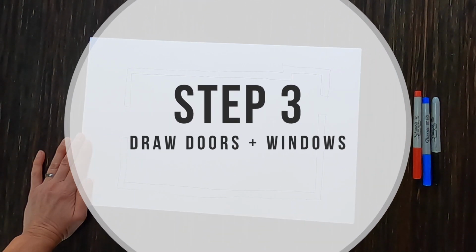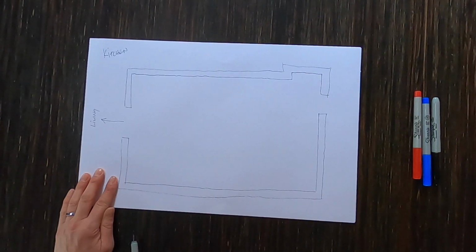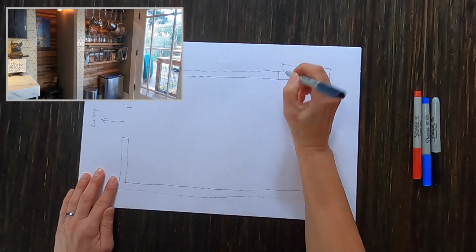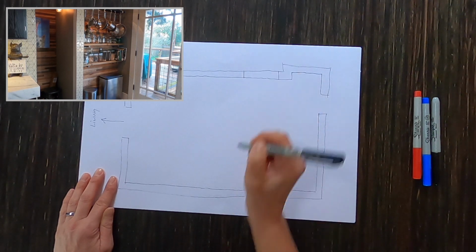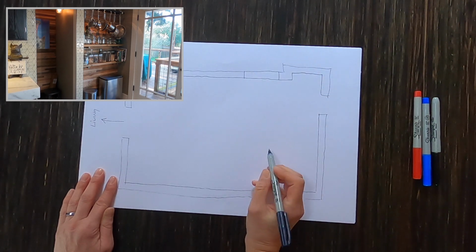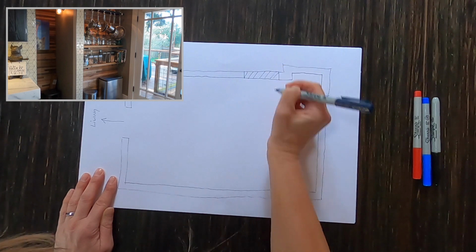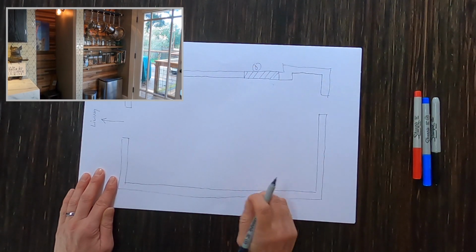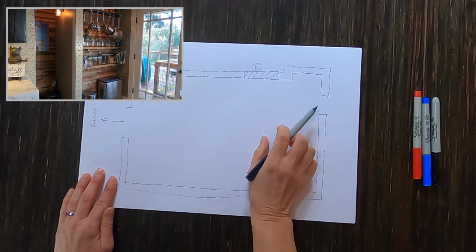Okay, let's look at each wall individually and add our windows. We have an opening to the basement, which is pretty close to this wall niche. Okay, so we have an opening here. How I like to do that, if I add doorways after the fact, I'll draw my doorway opening lines and then just kind of hash anything like this. That means it's removed. And then I just do a circle with a D. There's my door. Then we have our wall niche.